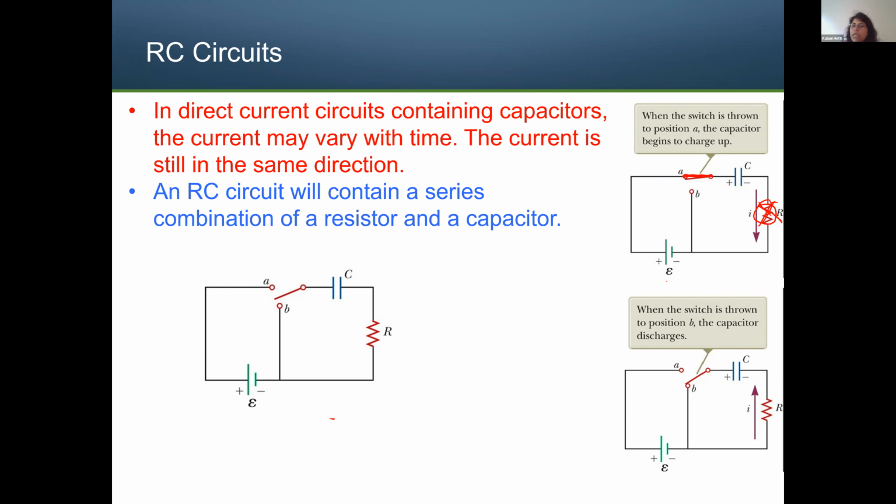So now when I connect the circuit, I know some charges will be pumped from the power supply and go through the circuit, and this is charging, right? And what happens to the light bulb? The light bulb is going to light up. Sometimes you will see it dim, and then the light will disappear after some time. Why is that? Because your capacitor is fully charged, then there is no current passing through the capacitor. Then your light is going to disappear.